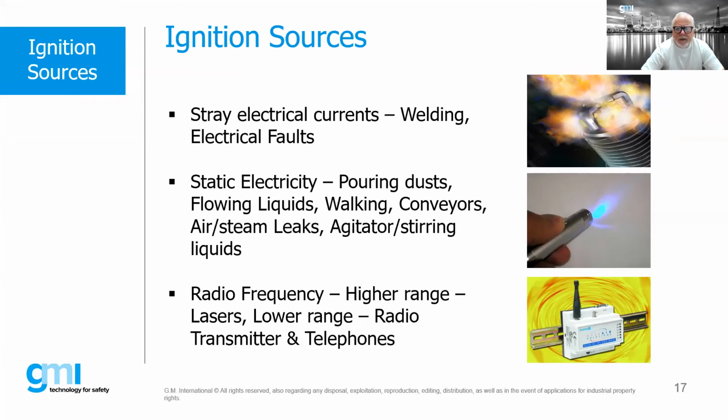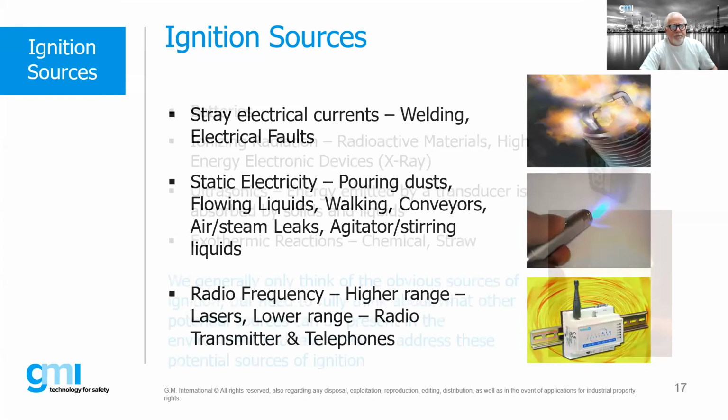Certainly, radio frequency is also a source of ignition. Taking our telephones, potentially not just an arcing or sparking, but some of the radio frequency, or not so much with telephones, but maybe with transmitters and some of the wireless products that you can see nowadays. The energy emitted is actually enough to ignite gases and vapors. So we have to be very concerned when we install equipment, depending on the radio frequency that's actually being used. We have to take that into consideration.